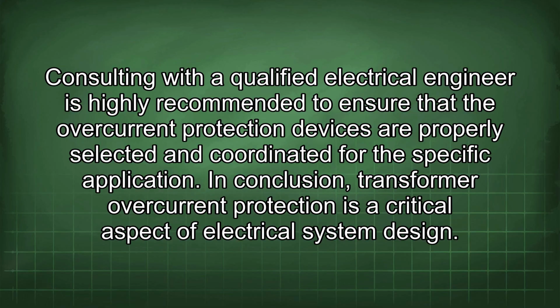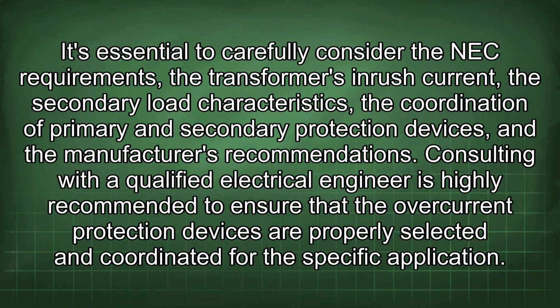In conclusion, transformer overcurrent protection is a critical aspect of electrical system design. It's essential to carefully consider the NEC requirements, the transformer's inrush current, the secondary load characteristics, the coordination of primary and secondary protection devices, and the manufacturer's recommendations. Consulting with a qualified electrical engineer is highly recommended to ensure that the overcurrent protection devices are properly selected and coordinated for the specific application.